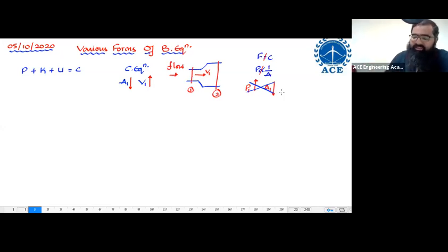No. Since V1 is high over here, the value of kinetic energy is high. Forget about potential for some time. The value of kinetic energy over here is high. If kinetic energy is high, who should be less? Pressure should be less. This implies the value of P1 is supposed to be less. This is the basic idea.